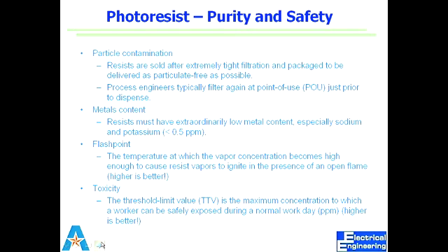Metals have to be very low because, of course, when you do bakes, you can get those metals to get incorporated into the wafer, which you don't want. Right? Flash points, yeah, you want lower flash point, right? Or not? These guys are sleepy. I'm saying lower flash point and nobody disagrees with me. We need lower flash point for resists, or not? Somebody says that higher is better, so we don't ignite it doing bakes.